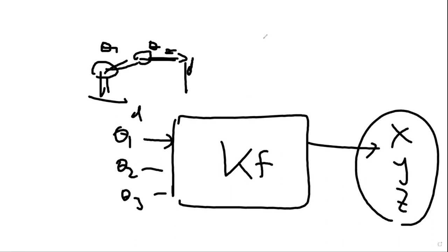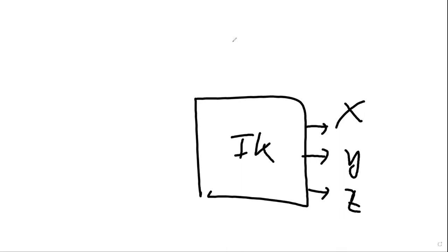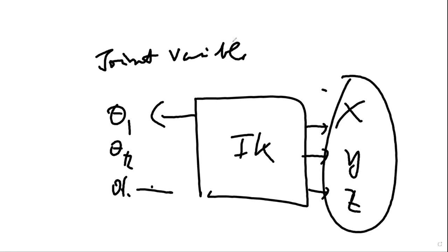Now, inverse kinematics means that we do have the desired, expected XYZ, and I need to come up with what theta1, theta2, d1, d2 need to be. So go back to find your joint variable values from the coordinates, solving the equations to get your joint variables.